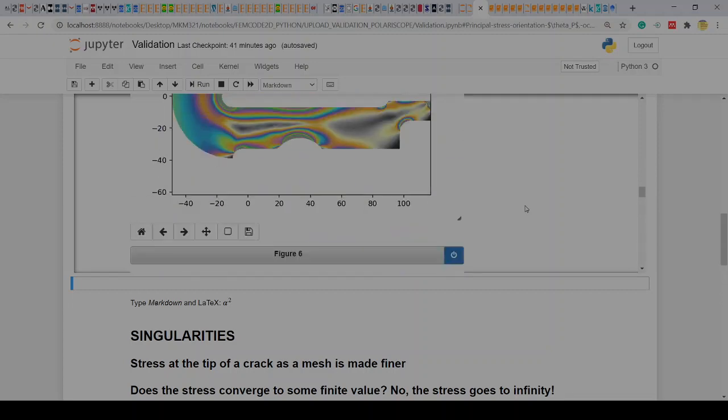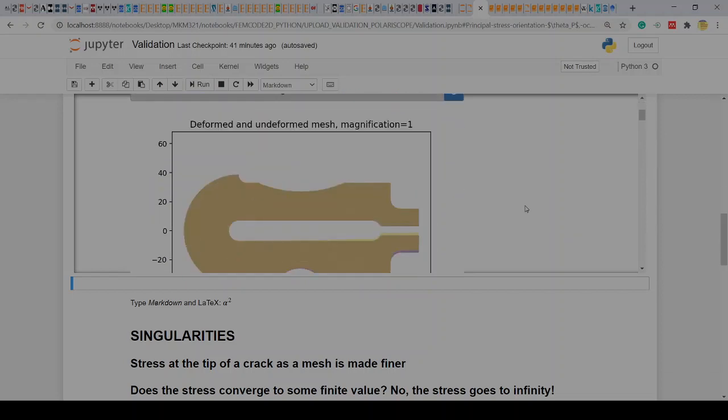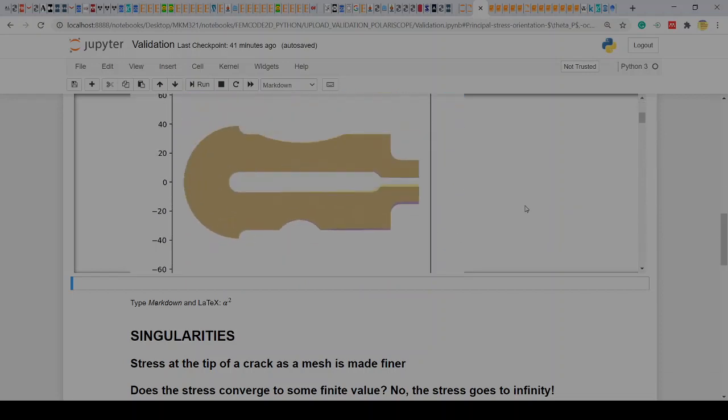It also is useful for calibrating models. So especially when you have nonlinear materials later on in your careers, when you take the postgrad FEM course, where you learn about nonlinear materials, so viscoelastics, plasticity, and those are things a lot more complex to calibrate. So an elastic material is easy. It's essentially, at least for isotropic ones, Poisson's ratio and Young's modulus. But then maybe composites, you require a couple more coefficients, maybe the Young's modulus in different directions, Poisson's ratios in various directions. But that's just about as complex as what elasticity will go. It's really via orthotropic materials, etc.